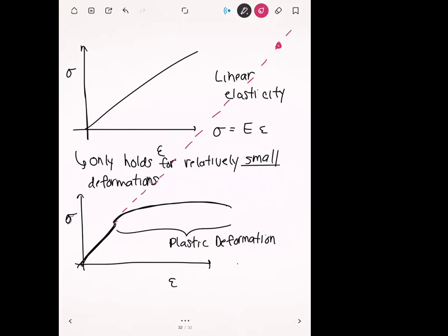The way I do it is I look at the general dimensions of my geometry. Let's take our plate, for example. The plate is 300 millimeters by 200. If I'm getting deformations on that same order of magnitude, like 50, 60, 70 millimeters, which is pretty close to how big my object actually is, then I would say that's pretty large, and I would have to turn on plastic deformation to make sure it's okay. Good questions though. Any other questions on this?